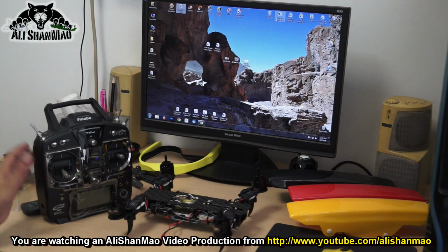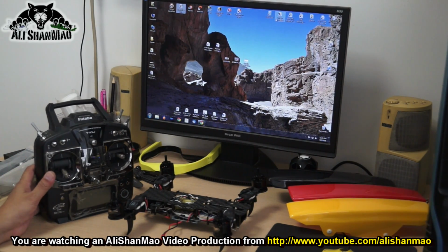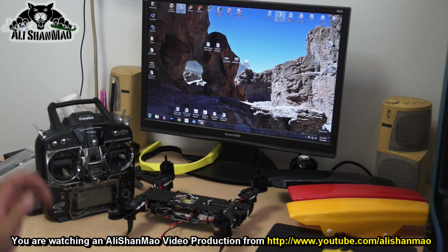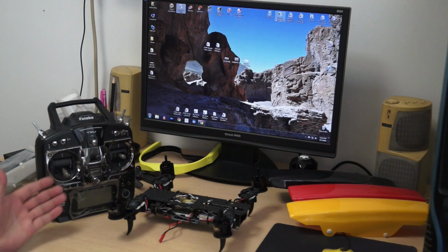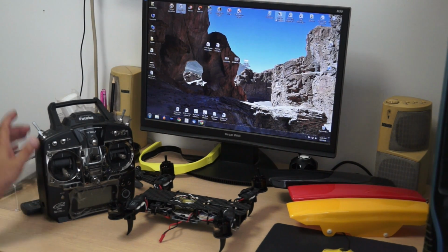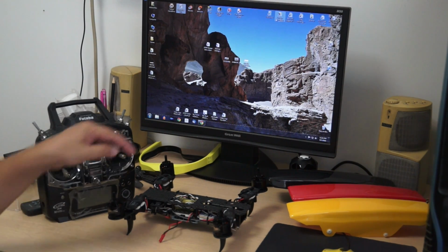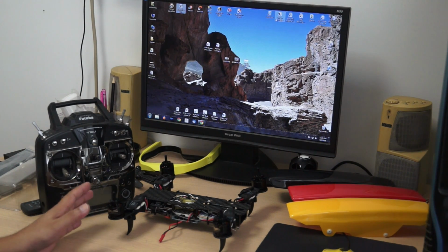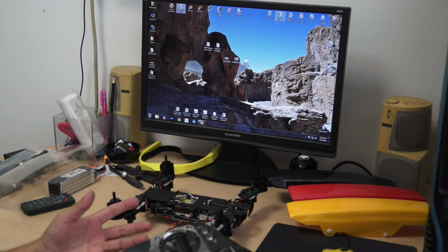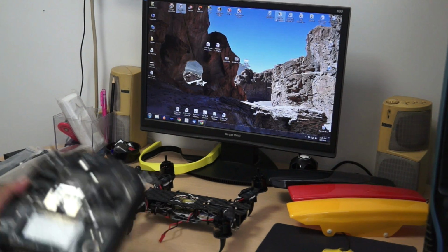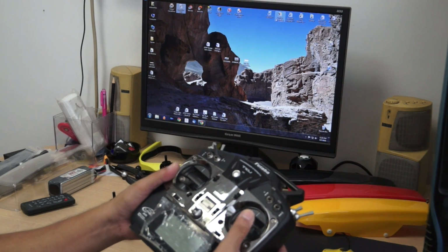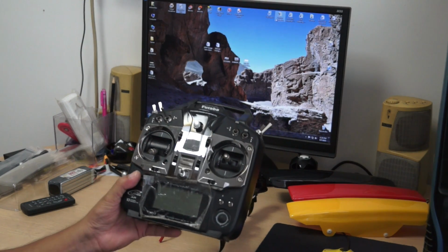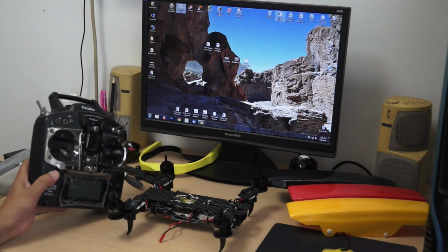Okay, to begin with, you will program the radio basically for a fixed wing aircraft, so that is a normal fixed wing aircraft, and you will leave your reverse setting to stock radio settings, because we can do the reversing of channels using the flight controller programming. So we are not going to touch there. Well, endpoints, we are not going to touch them. Dual rate and expo, well, that depends on the user's choice, how responsive they want their quad to be on the stick movements. So basically, to program the radio, it is very simple, piece of cake totally.